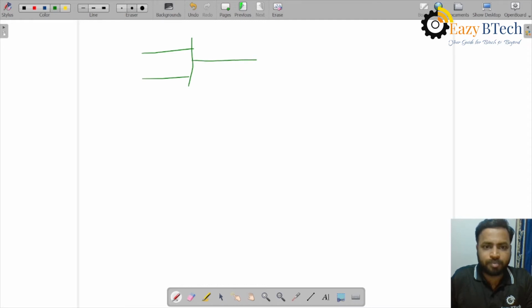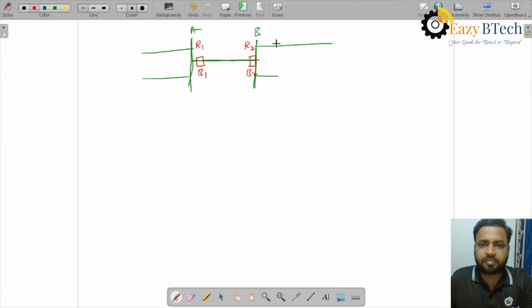Let me take a small portion of a large system. There are two bus bars A and B, and a line joining them. There is other power system here; I'm not showing the entire system. We are concerned about this small zone A and B and the line joining them. To protect this line, we have installed circuit breakers: breaker 1 and breaker 2, with a relay corresponding to each. Similarly, for each line there are breakers: B3, B4, and of course relays R3 and R4.